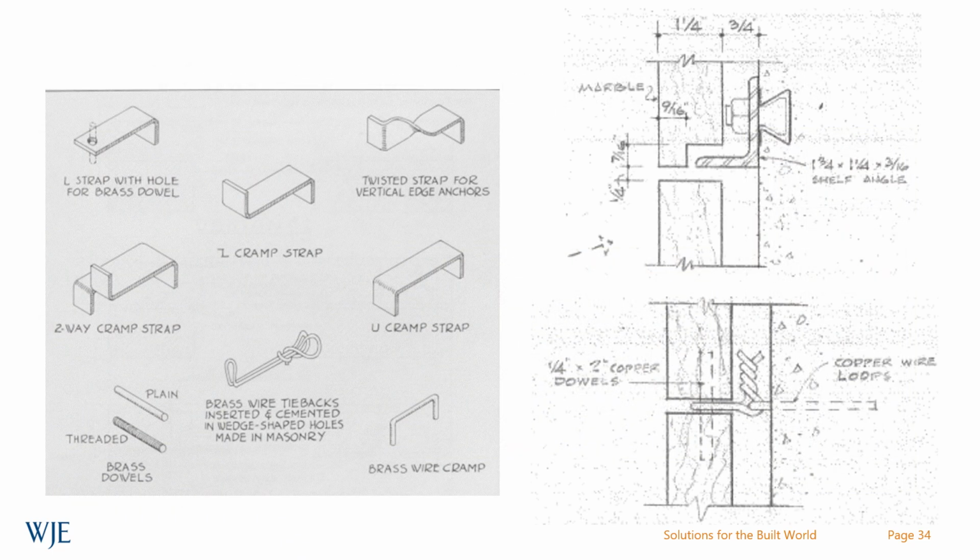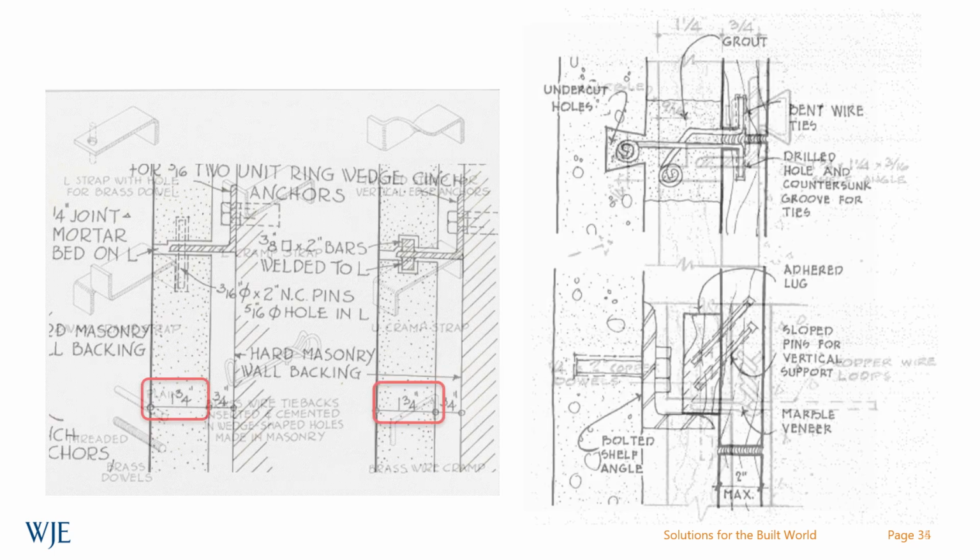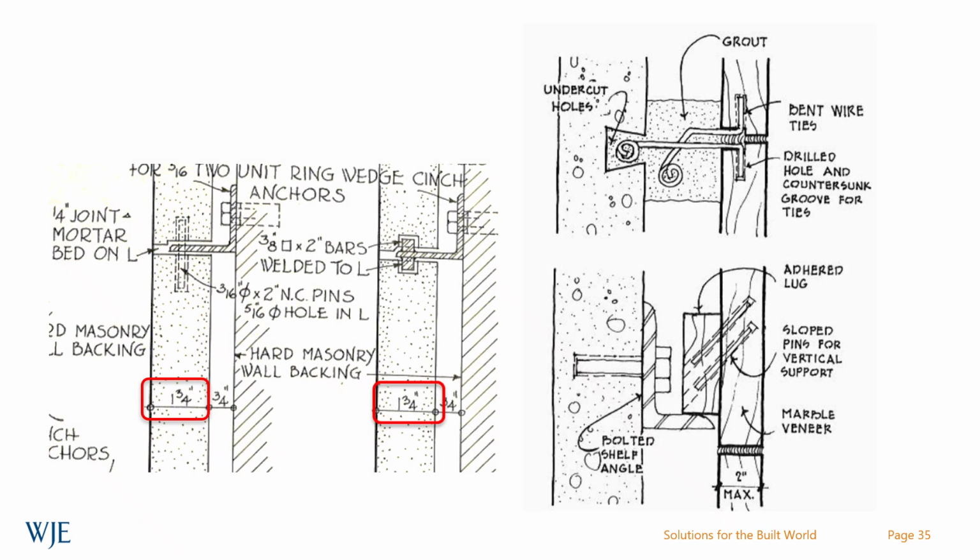These are some more details for some of the applications where you have off-the-shelf lateral anchorage shown on the left, and then you have an installation application on the right. Another example of some of the stone anchorage used during this period, we have very thin limestone panels on the left two images, and then liner blocks that were used on the right image for added gravity support, as well as some mortar blobs that were used for inward load.